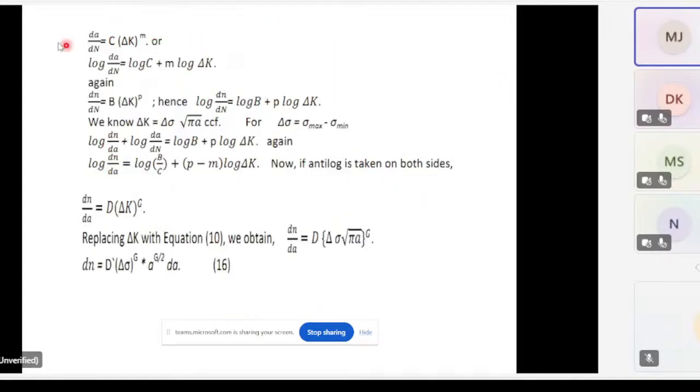Now, this is a famous thing: when exactly the crack will start propagating catastrophically, so that the failure becomes immediate. So that is the rate of crack propagation, da. When fatigue cyclic loading is there, the crack growth with respect to the number of stress cycles depends on the crack length and is given by some constant into delta K. That is, the initial cycle was K1, the next cycle K2, so K2 minus K1, raised to the power m. M is an exponential constant.